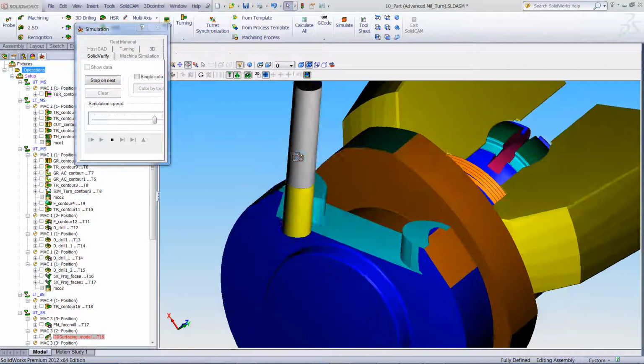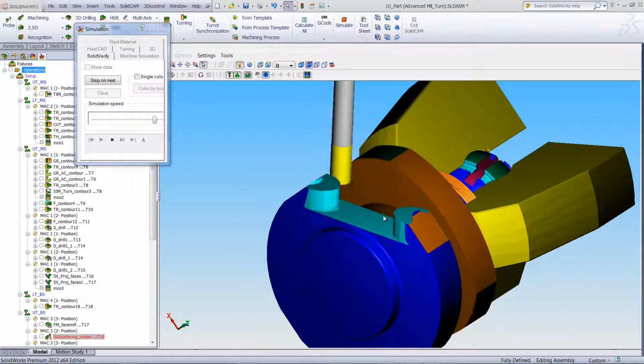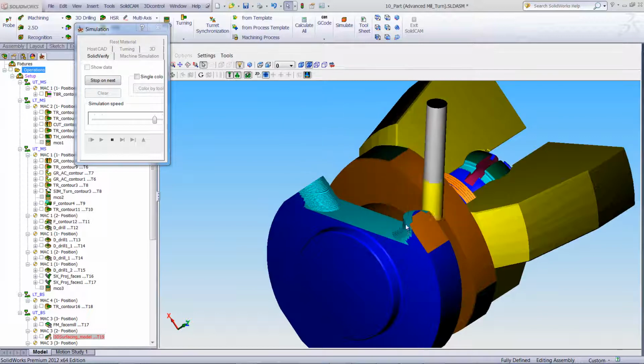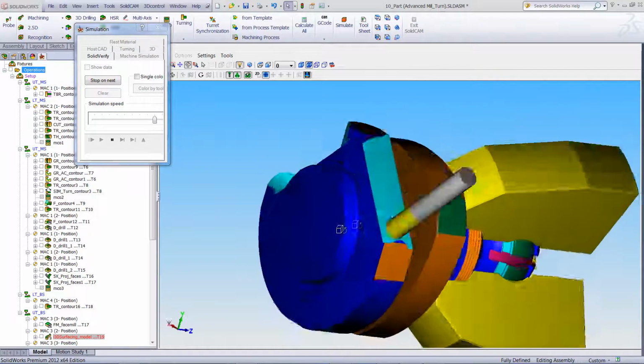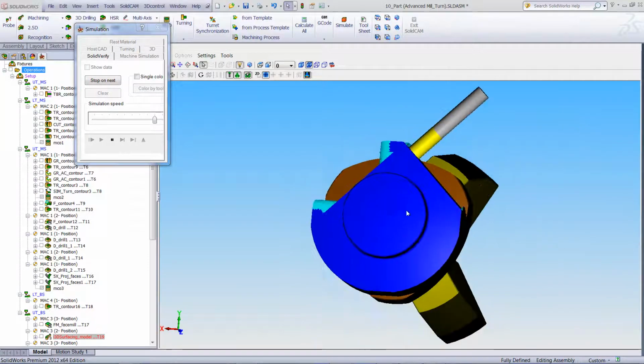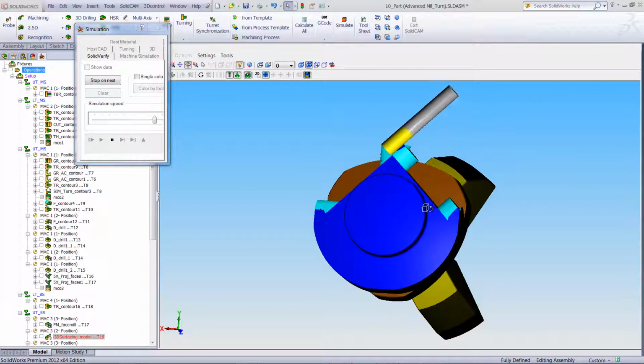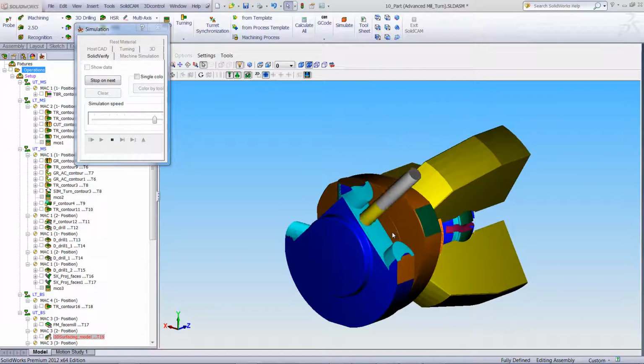And in this particular case, this area now is being machined out using the 3D I machining, working out these slots over here, stepping up. And then we just did a simple indexing to do it on the other sides as well, milling out these areas, again using the 3D I machining.